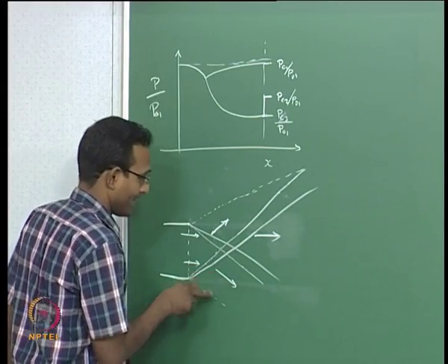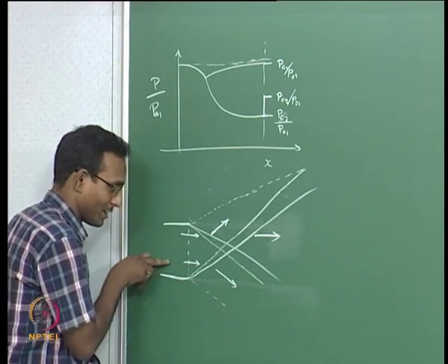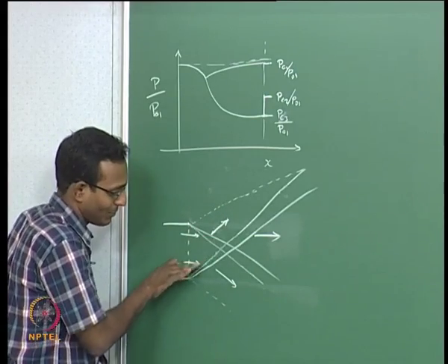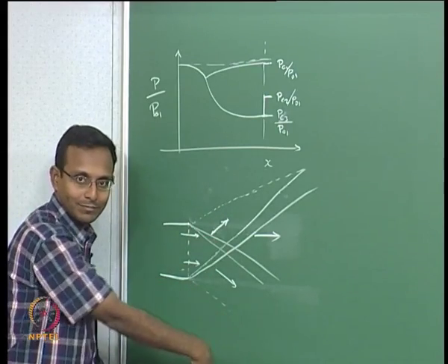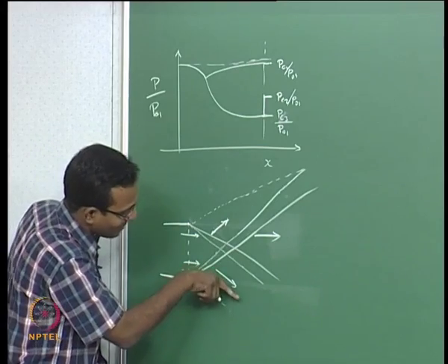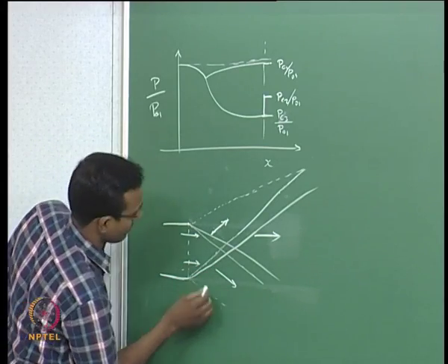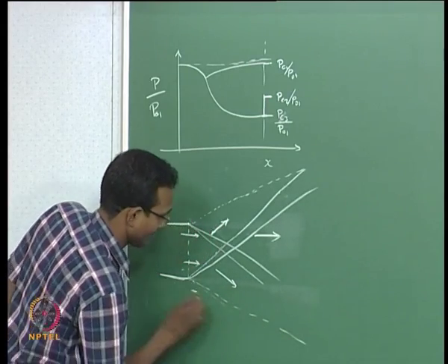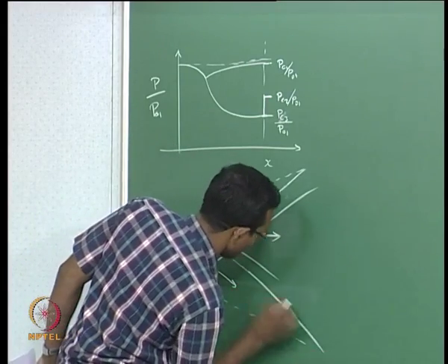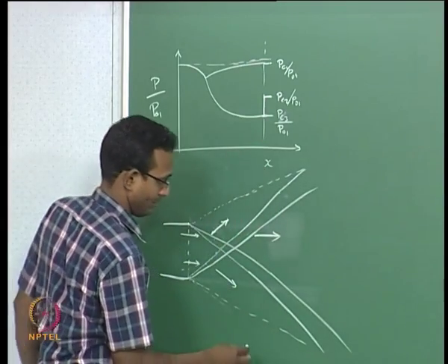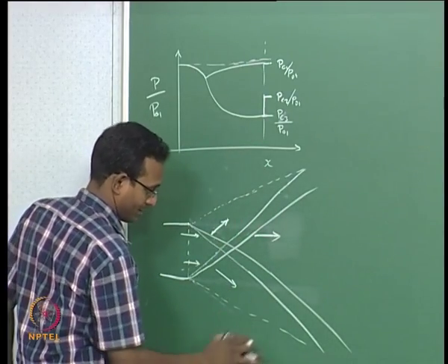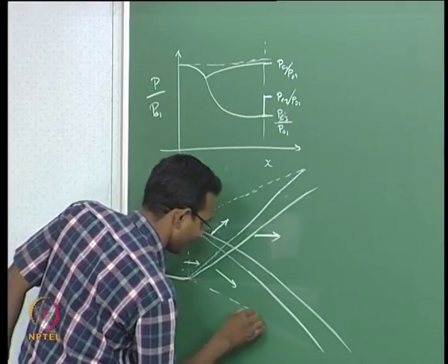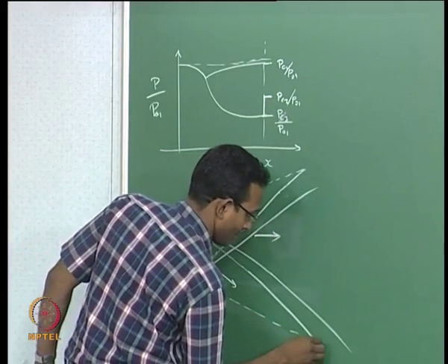Same thing will happen this side. I am talking about this fluid element now, it is first facing a left running expansion wave, which means the fluid is accelerating to the right, okay, and immediately after that I keep going, I have to draw it symmetric also. This expansion keeps going like this, looks like I am not drawing very symmetrically, I will try and match the top one, close enough.